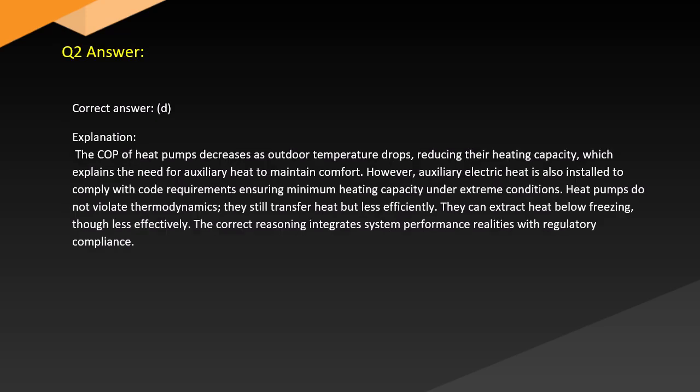Answer. Correct answer: D. Explanation. The COP of heat pumps decreases as outdoor temperature drops, reducing their heating capacity, which explains the need for auxiliary heat to maintain comfort. However, auxiliary electric heat is also installed to comply with code requirements, ensuring minimum heating capacity